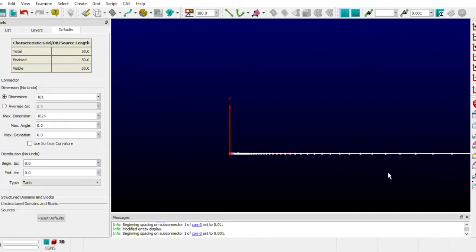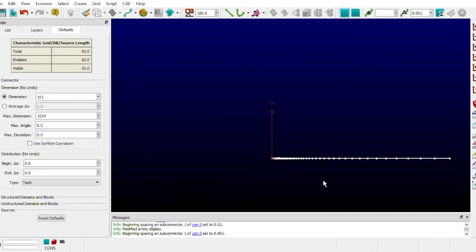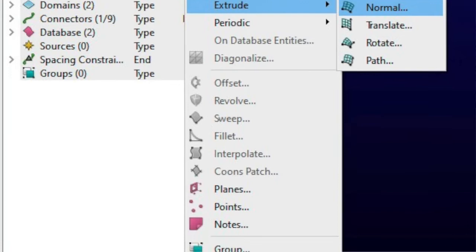To significantly support the values and collect all the mesh data, we need to have a clear straight distance from the airfoil of approximately half of the chord length in front, which is on the C-grid. That's why I chose 50, and later on we will extend the whole dimension in order to get a wake section to collect all the after effects from the foil, which will give us another block dimension of another 50 or another 100 length, which will collect all the wake effect from the airfoil's inlet flow. Now the next step is creating an extrusion, which I'm going to use on a normal section.